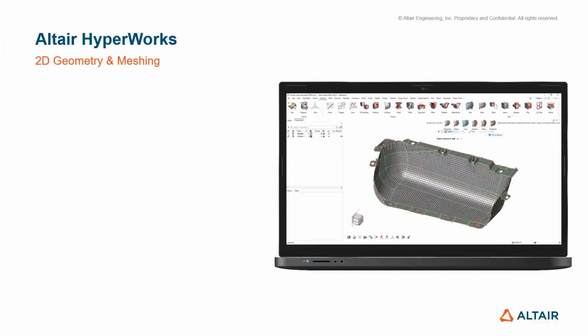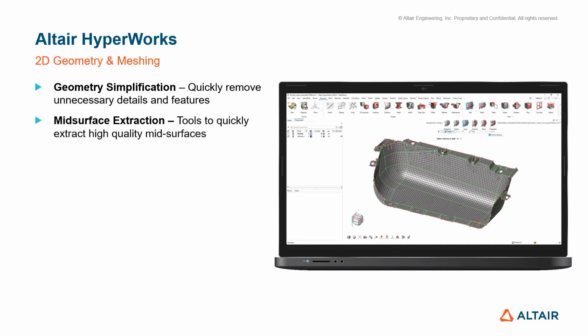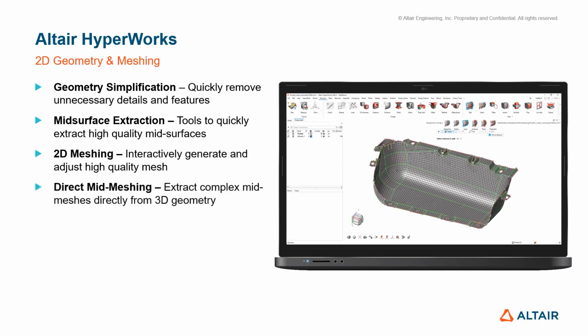So that brings us to the end of this session. We've looked at geometry simplification, so how we can quickly remove unnecessary details and features from the CAD. We extracted our mid-surface using the mid-surface tools and showed how they could be completely automated with also manual control. We looked at 2D meshing, how we can interactively generate and adjust a high-quality mesh. Or for complex geometries, use direct mid-meshing to directly extract the mid-plane mesh without the need for the mid-surface.